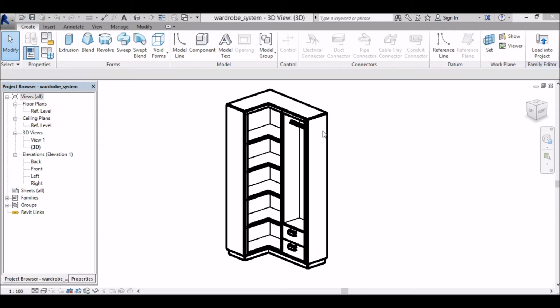So if you had a parameter for wall material, you might want to link it to timber, for example. And the second process is that you then need to apply those parameters to the different areas of the furniture. So it's very much like what we've already done with applying length, width and height dimension. And this is all done through family types again.